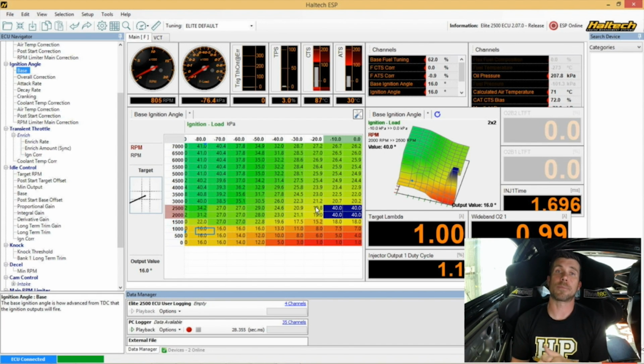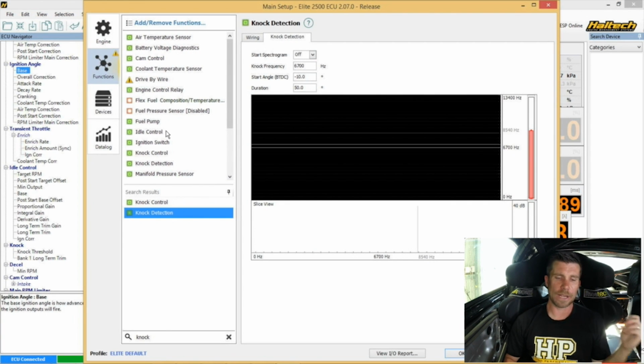Now I know from my prior testing that is enough on this particular engine to generate some detonation. While you're doing this, obviously I would strongly recommend that you use knock detection equipment. Alright, so we'll go back, we'll get our engine running now in 4th gear, and we'll just have a look at our spectrograph and see what actually happens when we create some knock.